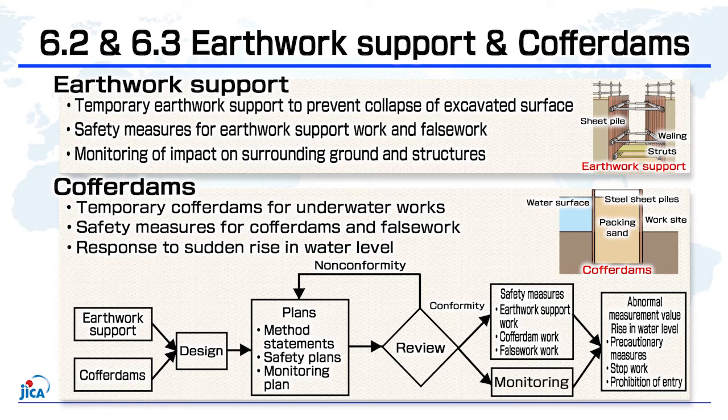Sections 6.2 and 6.3 specify the safety requirements for earthwork support to prevent collapse of excavated surfaces, and cofferdams for underwater works. Section 6.2 covers the planning, design, method statements, safety plans, and monitoring plans for earthwork support, safety measures for earthwork support, and monitoring of surrounding ground. Section 6.3 covers the planning and design of cofferdams, method statements, safety plans, monitoring plans, safety measures for cofferdam work, and response in the event of a sudden rise in water level.